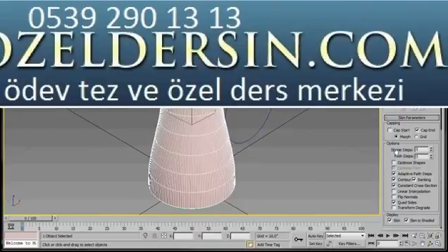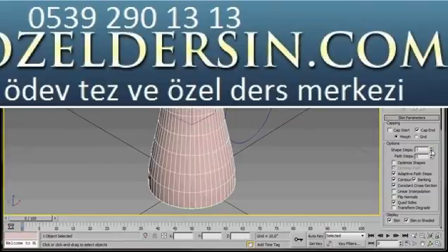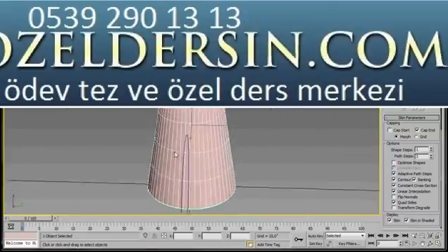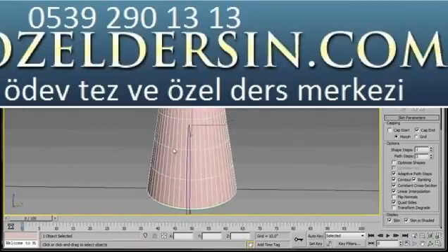Let's pop back over to the panel and have a look at the Options. Here in Shape Steps, I'm going to bring them down to 1. And Path Steps, we'll bring these down to 3. Look at our geometry. It's a lot better now. I'll just have a look. I have Adaptive Path Segments turned on. And also I'm going to turn on Linear Interpolation. That's just going to give me a straighter look. Okay, let's have a look. I think that's coming along quite fine.